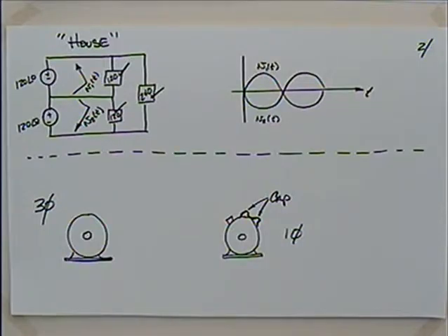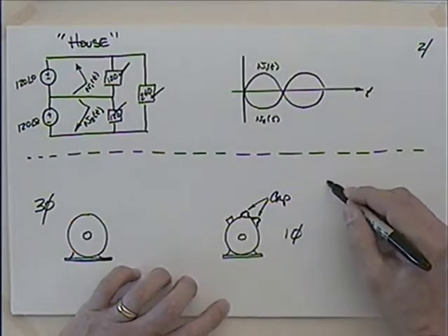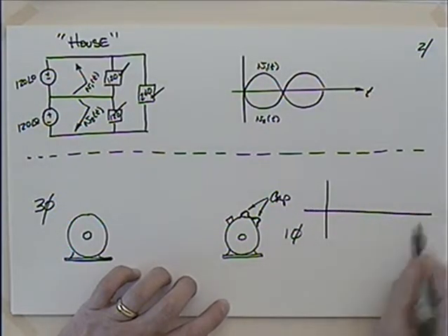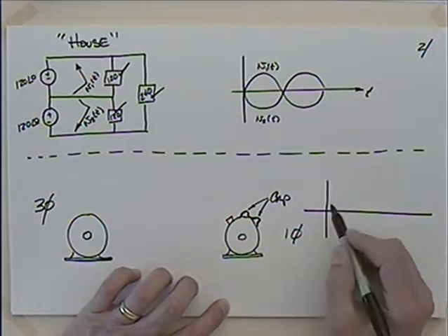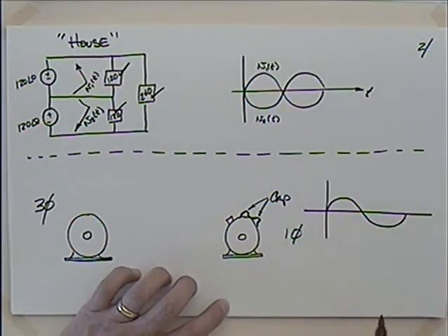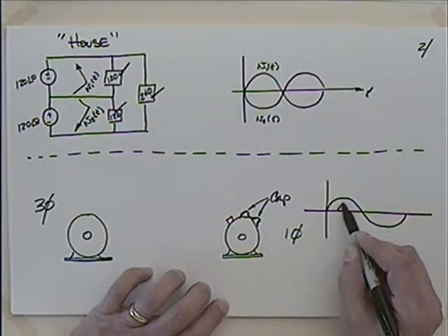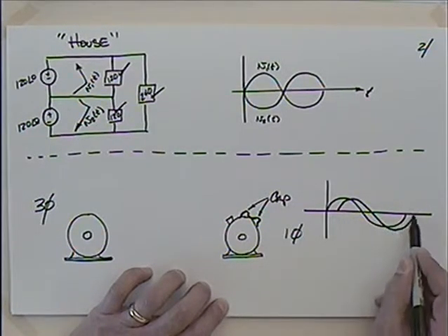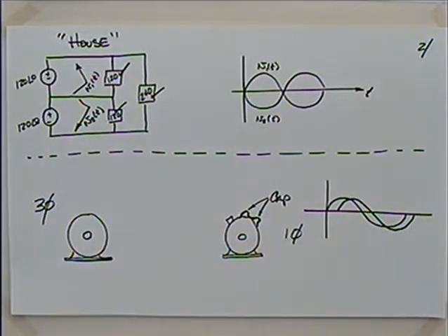Yes? So why do you have the capacitors on the motors? Yeah. If it's such a quick frequency, 60 hertz, that's pretty fast. Yeah. So if we take this single-phase signal like this, a lot of times, and let's pretend they use this capacitor all the time, not just for startup, they'll use that capacitor to shift this so now they have something like that, so they can get more torque out of it. Yeah.